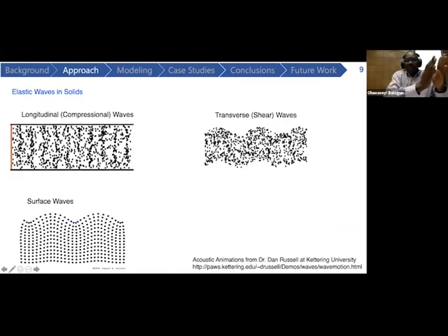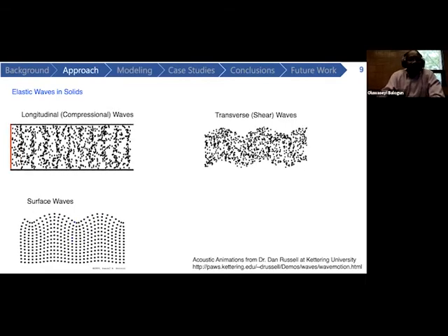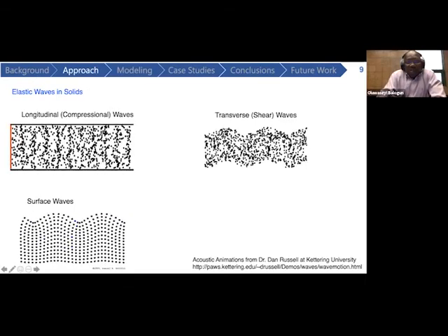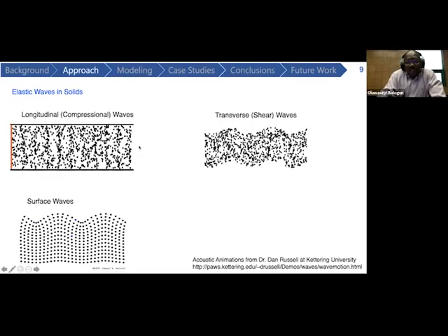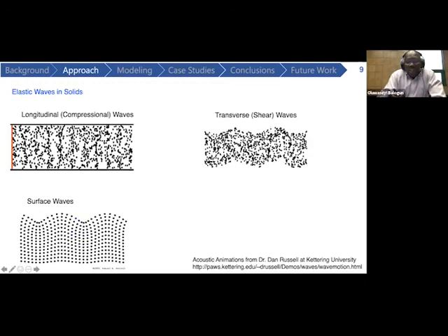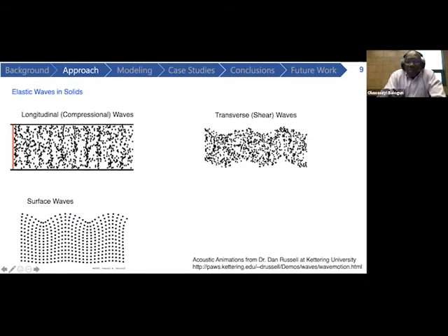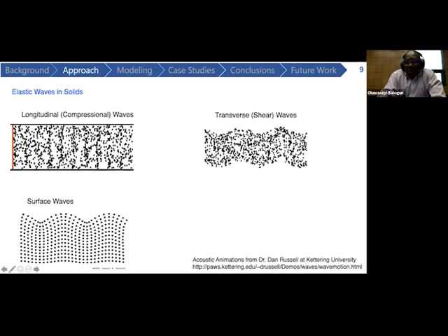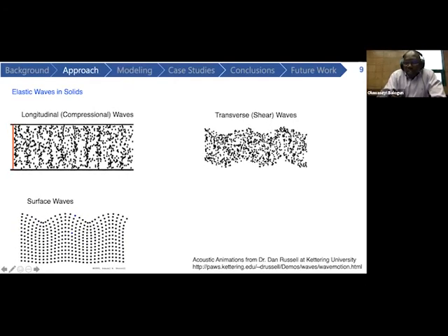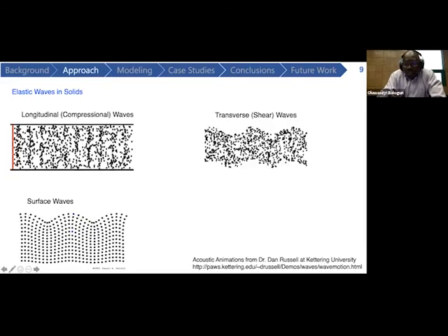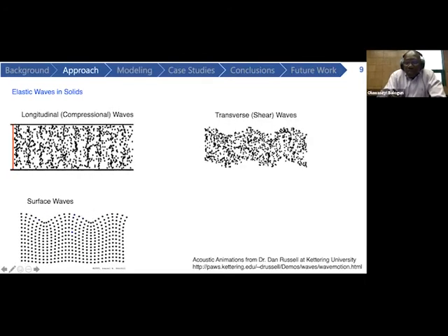And as a result of that, you see this energy flux travel from the left to the right on the screen. That's a compressional wave, in which the propagation vector is along the horizontal direction and the particles are moving along the horizontal direction. We also have shear waves. Shear waves consist of waves with orthogonal polarization to the direction of wave propagation. So the waves are traveling from left to right and the particles are moving up and down within the material.